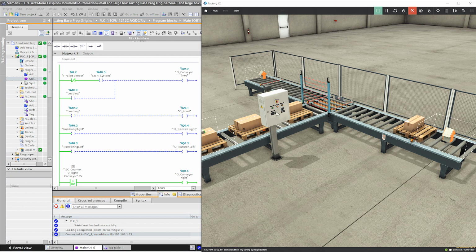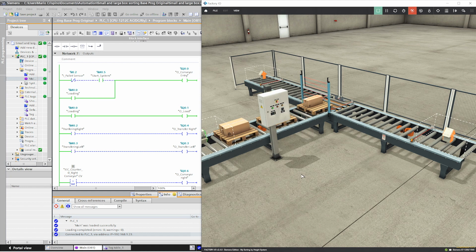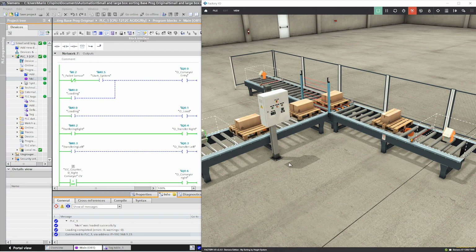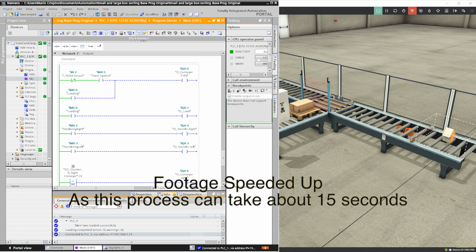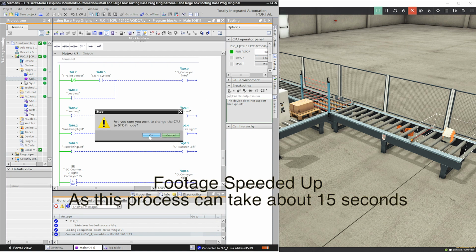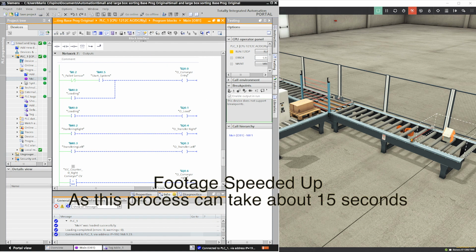Now let's press the start button again to make sure I did everything according to plan. The entry conveyor starts again, then let's stop it again. Well, try at least. Wait for it. Yes, that has stopped the entry conveyor. I think we can see the system is working okay. So let's stop the PLC and go offline. Then we can start programming the emergency stop button.